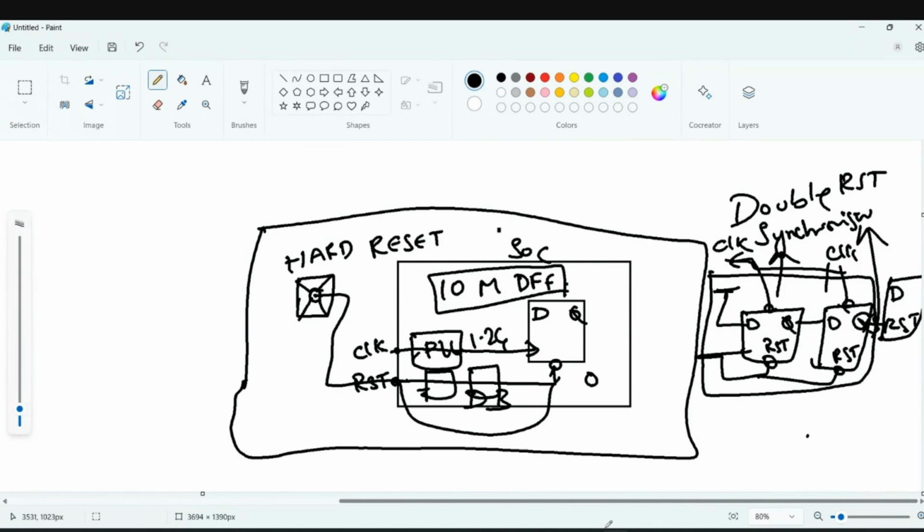In the 3rd clock pulse, you will see the synchronized reset coming in. This is the value that will be going into all the flip flops. However many 10 million flops there are in the design, all will have this reset coming in. So these synchronizers will be in the early stage, in the beginning of the design. The synchronizer output is given to the next flops. You will understand this at larger scale once the DFT starts, so don't worry now.